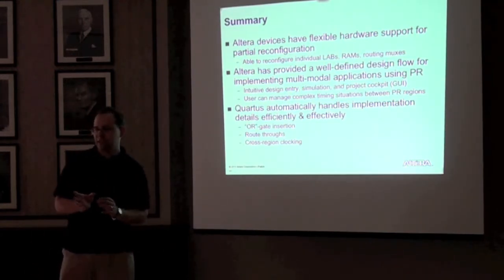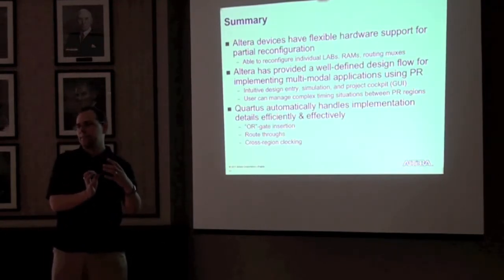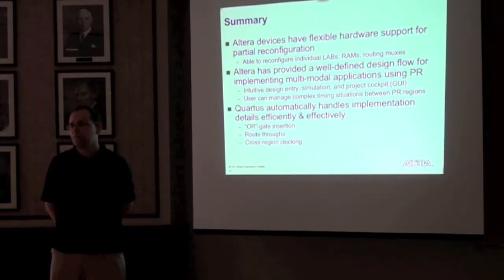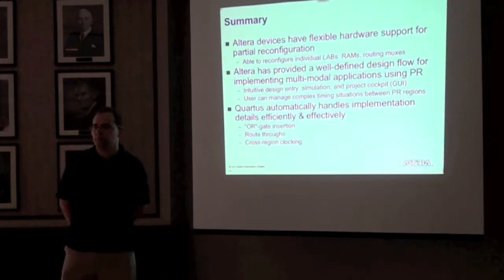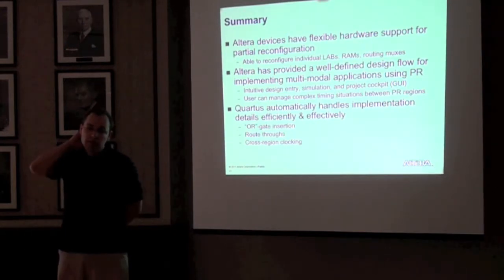So I'm not sure I fully understand the question, because even if you guarantee the anchor LUTs, that doesn't say anything about the internal state. If the anchor LUT output is being used to keep the PR logic in reset. So let's say I'm initiating PR external to the chip with a scan chain or whatnot. Once that's done, I don't want to have to figure out a way to insert an I/O or something like that to let the static region FPGA logic inform the PR logic, okay, now you're free to go. It's ideal if you could just do it itself.